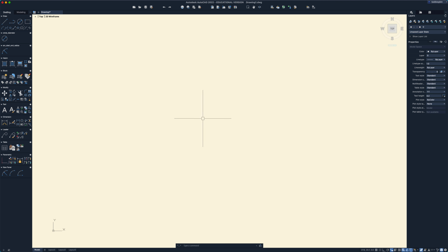All right, now we don't really need to have our limits, but our drawing is basically 450 wide on the front and 350 wide on the bottom. I'll probably put a space of 200 or 300 in between. So somewhere around 1500 to 2000 wide units, millimeters in this case, and 2000 high is going to be big enough.